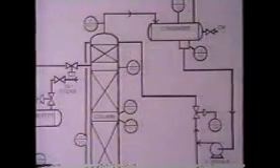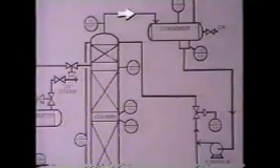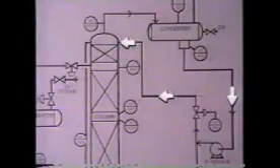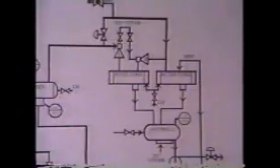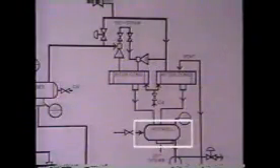Meanwhile, the lighter component, known as the overhead product, rises to the top of the column as a vapor. This vapor is routed to a condenser, which cools the vapor and turns it back into a liquid. The liquid is returned to the column as reflux. Once the overhead product is pure enough to meet product specifications, a portion of it is pumped to the overhead product recovery tank. This system operates under a partial vacuum. A pair of steam jets is used to create that vacuum. As the jet steam is condensed, it flows to the condensate hot well tank.